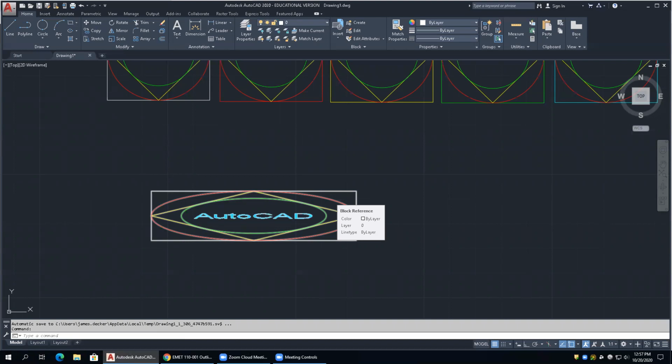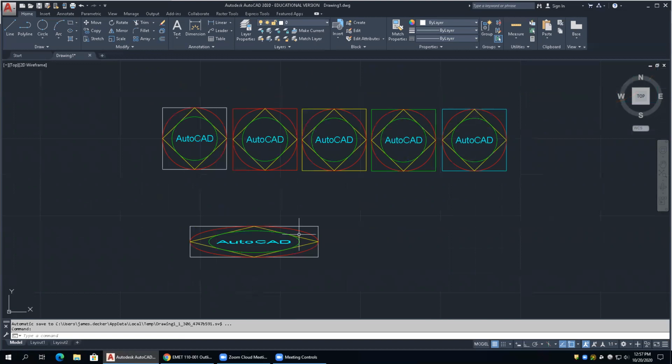Here's something really cool about scale factors. Let's say we want to mirror image this block. So instead of this going left to right, I want it to go right to left. You can enter negative scale factors. Watch this. Go into logo, go into the X scale, tell that -1 and hit enter.